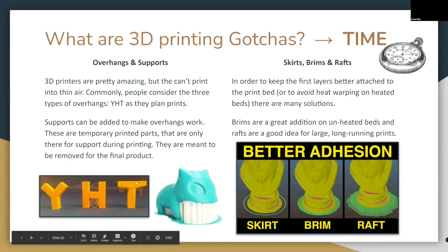And then a T is where it's real tricky, right? You're trying to draw out this T and you can see this went poorly. The first few rows aren't going to go well until you get some scraggly ones there that can then act as a foundation for the rest of the letter. So most of the time, this is an unacceptable result for a 3D print. There are some really cool prints that have happened where they deliberately make overhangs occur. Like there's some tree designs where they're trying to make it overhang so that the natural scraggly shapes become the leaves and branches of a tree that look kind of organic.